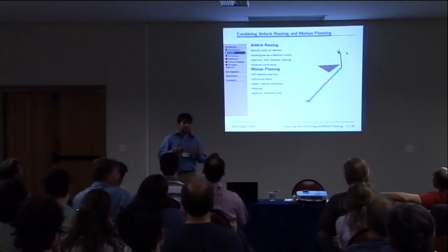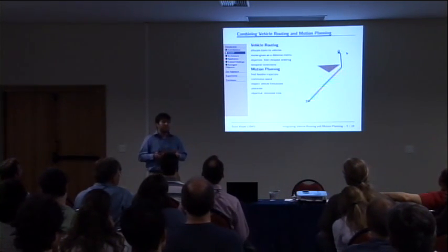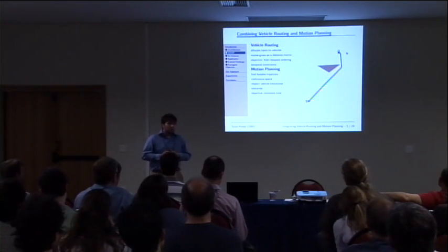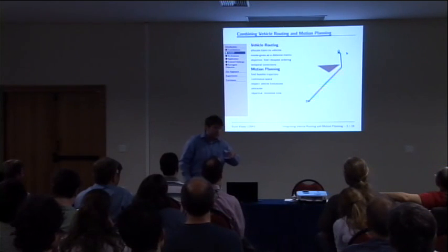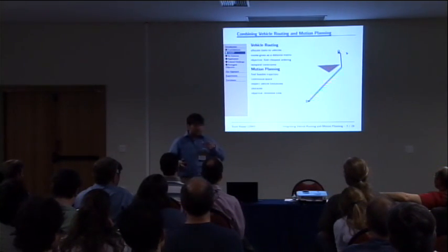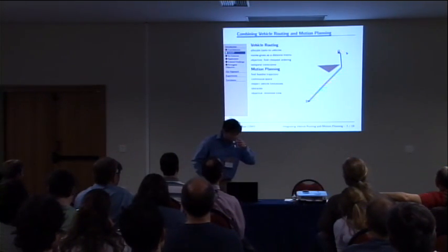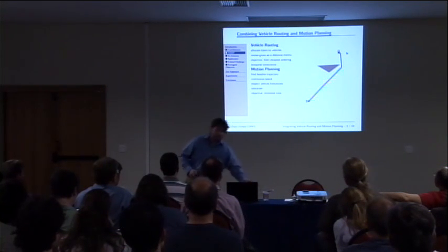Motion planning is the task of combining a start configuration with an end configuration, trying to find a feasible trajectory to do that over a continuous space. Moreover, we need to respect the vehicle's dynamic limitations as well as avoid obstacles while minimizing some cost function. Typically, it's time though.